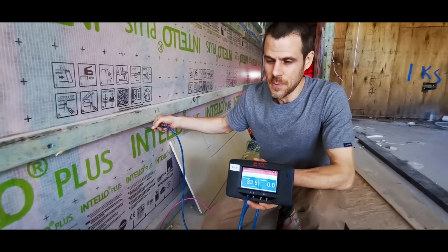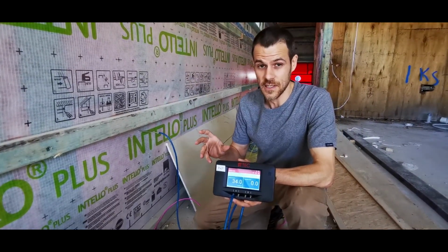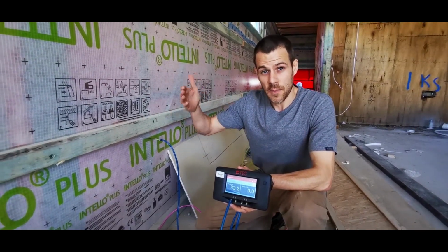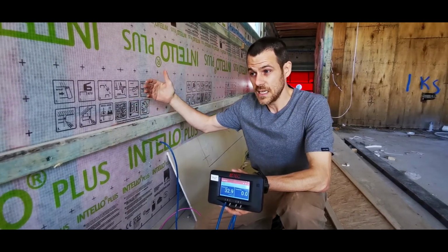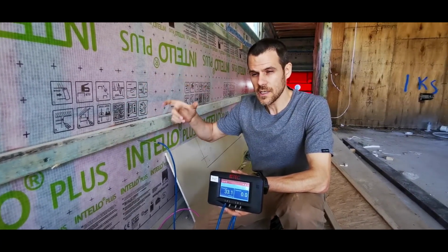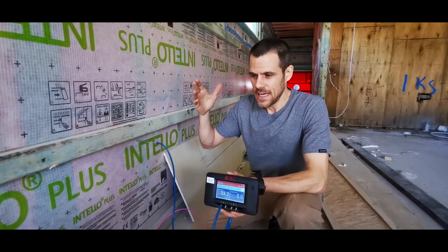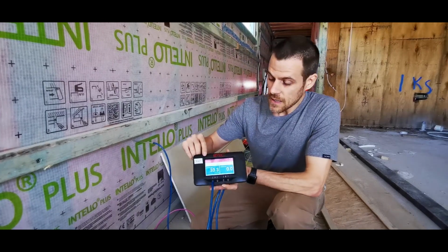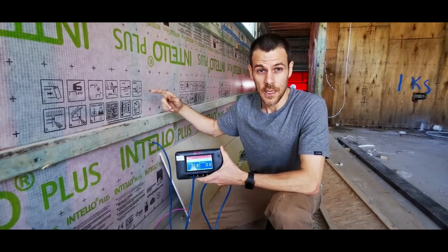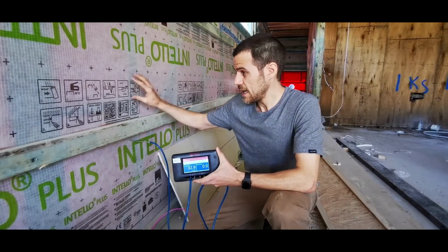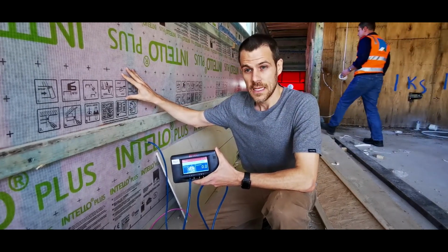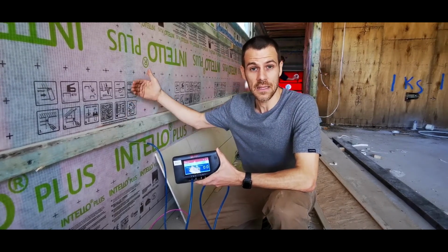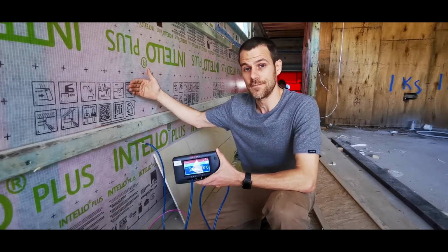Here's how this is supposed to make sense. I'll give some graphics to show you more, but if you have multiple layers of airtightness, multiple membranes, exterior weather resistant barrier, interior air barrier, and you want to know where is the problem. This is a really gross simplification of this, but here's what it means. If we're reading 50 pascals across the entire envelope, but only 33 pascals across the interior air barrier, that means that some of that 50 pascals is being taken by the exterior weather resistant barrier.